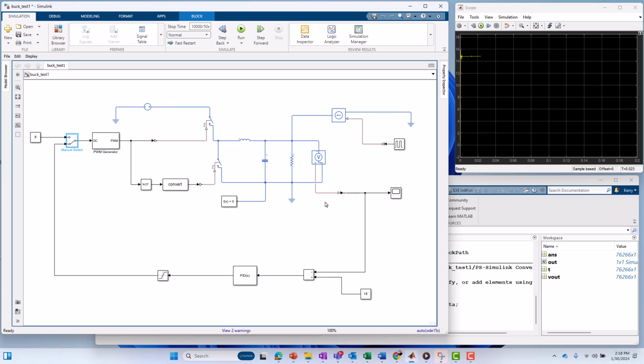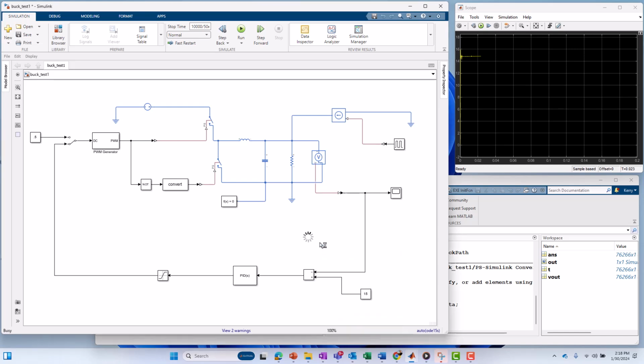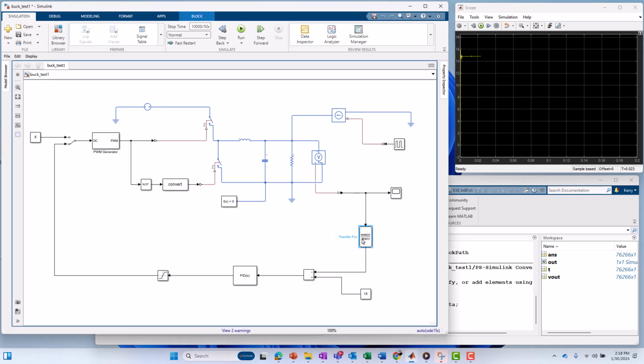So let's do that. One way to break a loop like this, a zero delay loop, is to insert a very, very small, infinitesimal type of delay into the loop. Of course, our goal here really is to model reality as close as possible. So what I'm going to do is just say there's some type of circuitry or measurement delay on the voltage measurement, the output, and I'm just going to model that. So instead of a finite, perfect delay, I'm going to pull in something that would have a group delay associated with it. I'm going to pull in a single pole low pass filter.